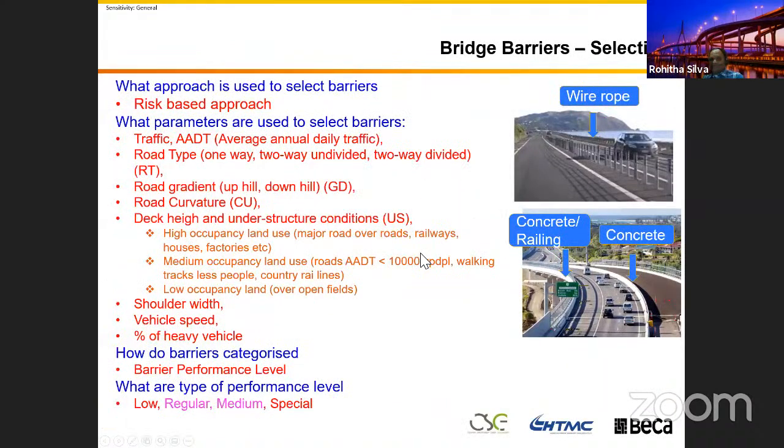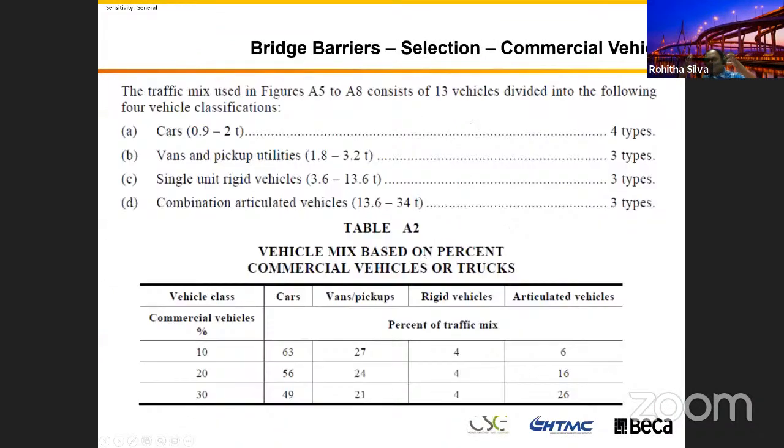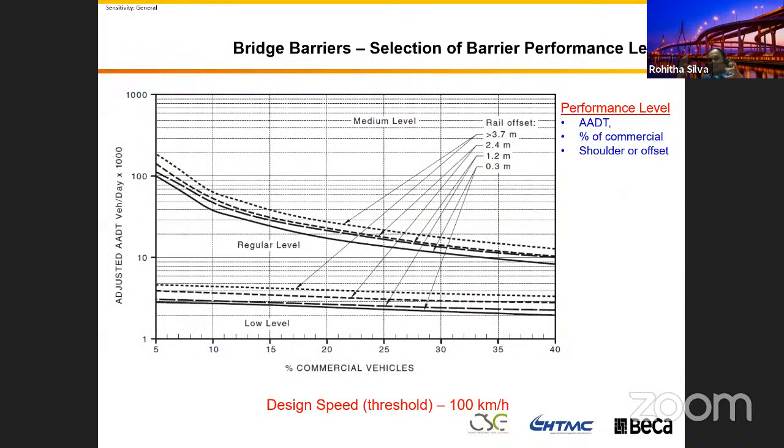You can see the lateral restraint we talked about, we need a minimum of 500 kilonewton for every pier. So in one span, if you put the minimum 500 lateral restraint at each end, you get a minimum lateral restraint of 1,000 kilonewton. That 1,000 kilonewton would be able to absorb any truck hitting your barrier and hold your superstructure in position without letting it move. You can see why we need them. It's very important. Your truck may hit the bridge, crash through the girder, and might fall down, but your bridge superstructure will stay in position.